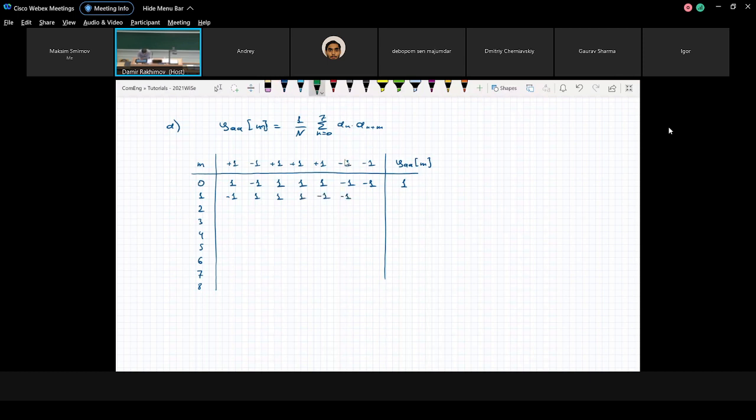And what should I place in the last position? 1, because this is a periodic signal. If we move by 1, on the right side we get the beginning of another period. For an energy signal we would have nothing and place 0, but for periodic we just write the beginning of the next period.